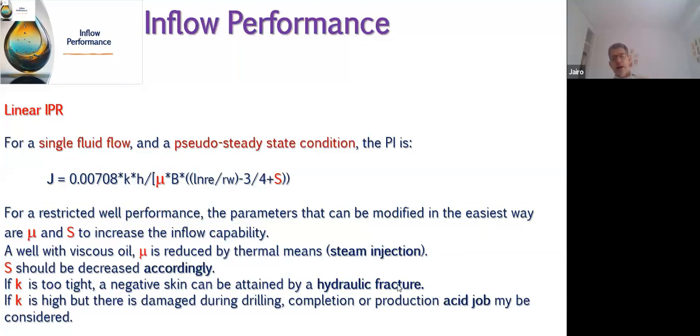One is hydraulic fracture, because in that way the final skin is negative, so it means -1, -2, depending on how well we perform that job. And the other one is acid in a carbonate. Those two are the real stimulation: hydraulic fracture and acid in carbonate.